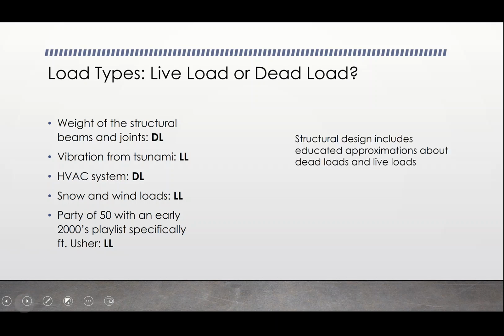So structural design includes educated approximations about dead loads and live loads. When people are thinking about, okay, here are my cabinets, they're going to be about 10 pounds per square foot, but that's not where it stops. We're not just going to throw the studs up and hope that they support 10 pounds per square foot of loading. Of course not. People have gone ahead and said, in those cabinets, they're going to put all their dishes, their KitchenAids, their baking sheets, whatever the case may be. That's increasing the cabinets' load to 40 pounds per square foot. And so that is what we will design our studs for, our wall supports.